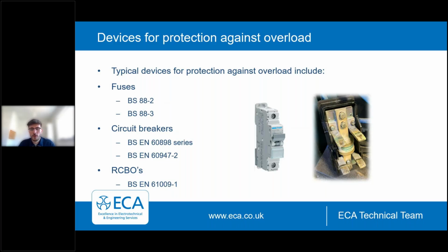When we look at overload protective devices and their operation, this is generally achieved by thermal devices. That means they take a period of time in order to activate and disconnect the circuit.